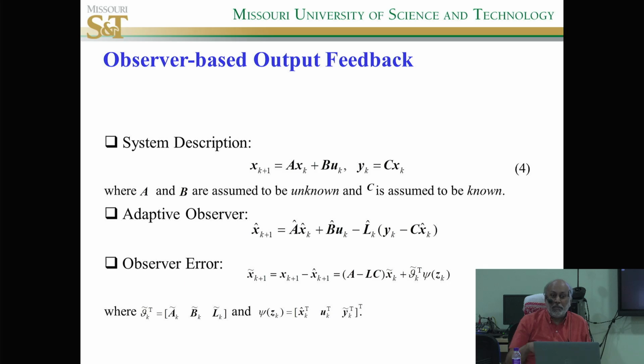Controllability is always with the A and B matrices. So B, AB, A squared B, up to A to the n minus 1 B, right? So what is the observability? C, CA, and so on. That we know, but we don't know what it means. So that's a danger, serious.